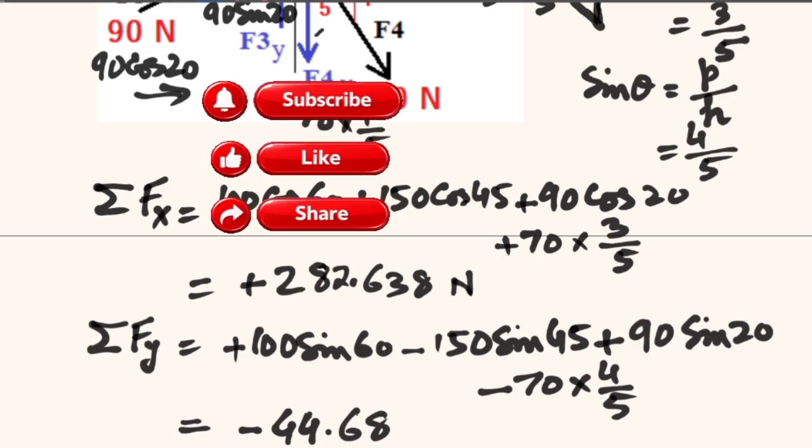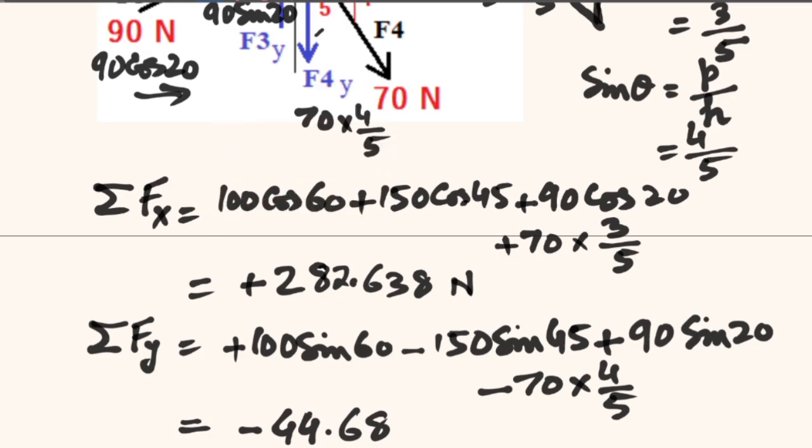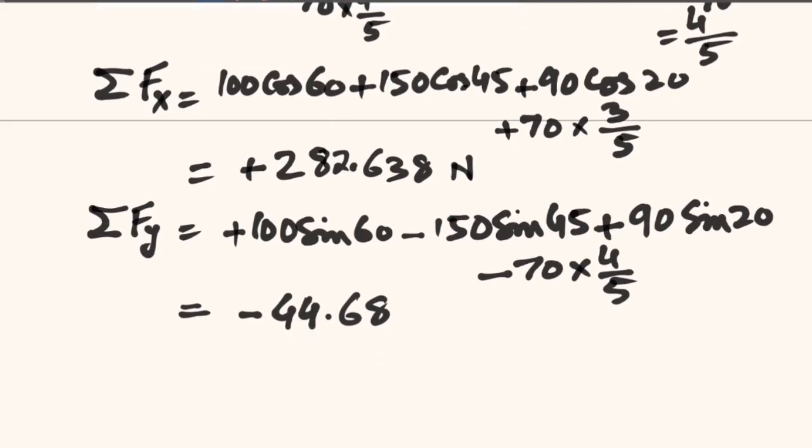So we have got the values of these sigma fx, sigma fy, which are the components of the forces, and this is the algebraic sum of the forces in x direction and y direction. So sigma fx and sigma fy can be used to calculate the value of this resultant R in this simple way.